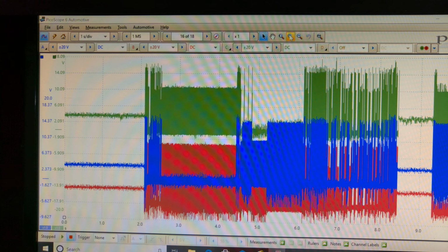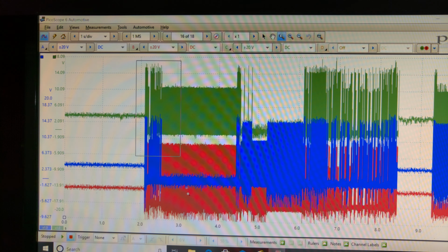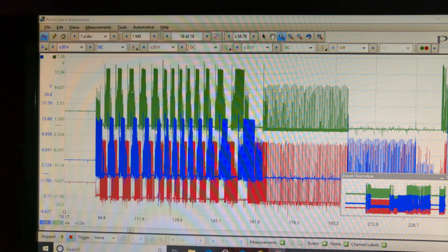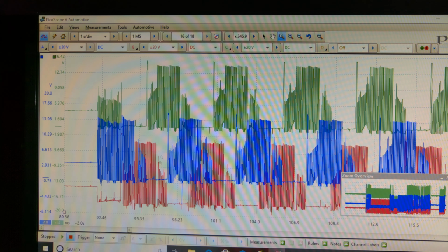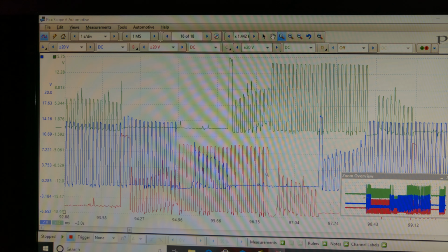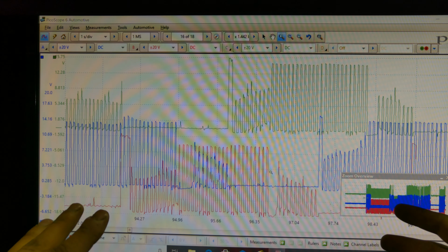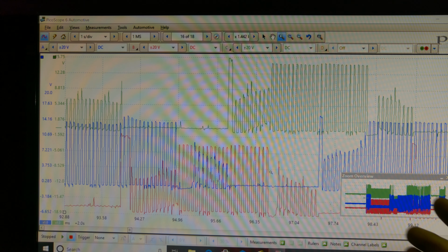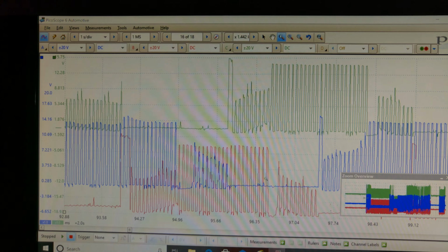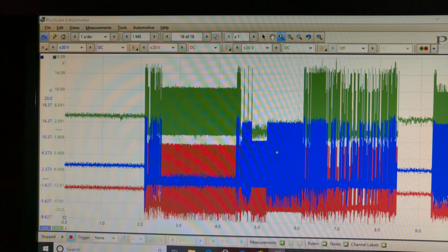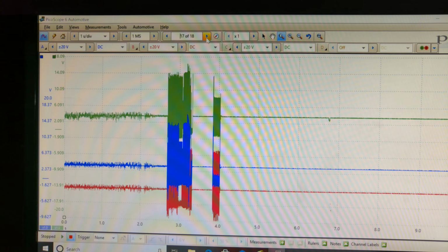So now let's zoom in and I'll show you what we're looking at in here, because it's a bit messy. So I'll just zoom in a bit more there. And yeah, we're basically seeing a duty cycle of 0 to 12 volts, actuator power and ground feed. We can go into detail and see which one's earth, which one's power, but I'm not too worried about it for this scenario. So we're just going to move on from here, and it stays like that until